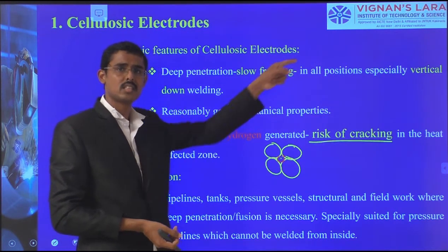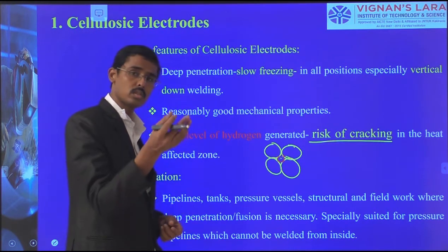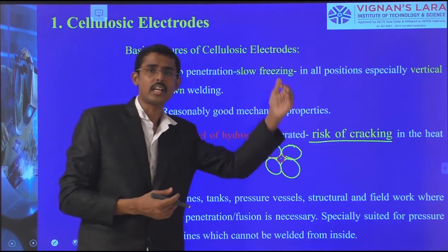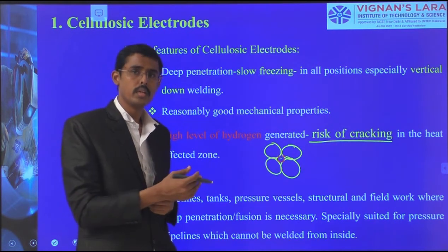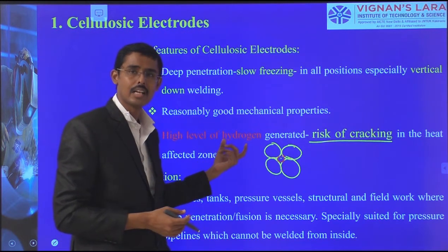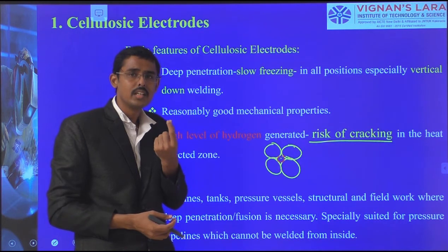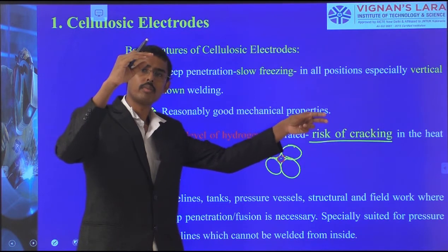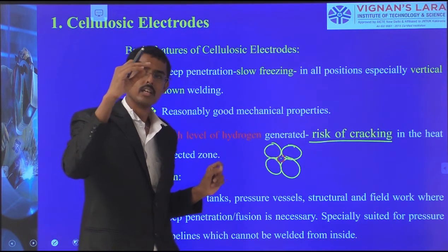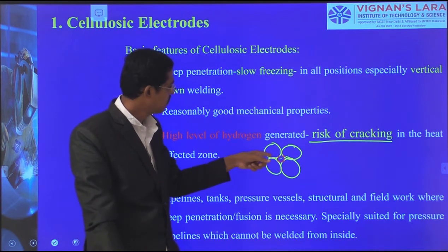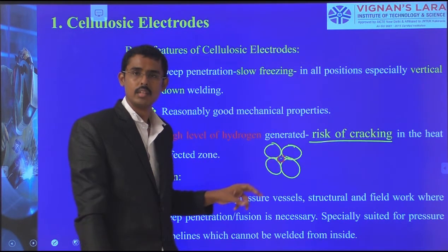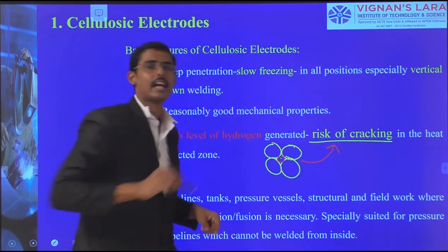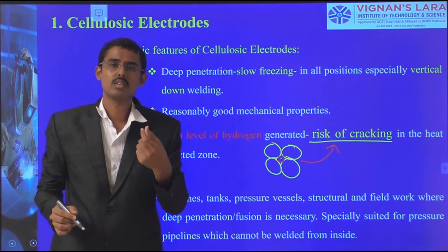The cellulose releases the shielding gas. There we have hydrogen. Those things are to be reduced, and the interaction with the environment also is to be reduced. The environment contains hydrogen. That is to be reduced. Those things should be taken care of. The hydrogen atom has less volume at high temperature, so it fitted there. This shielding gas absorbed from the environmental impurities is fixed there. But when the temperature comes down, its volume increases and it disturbs the nearby atoms. Therefore, it pushes, and the stress created initiates crack propagation, which is named hydrogen embrittlement.